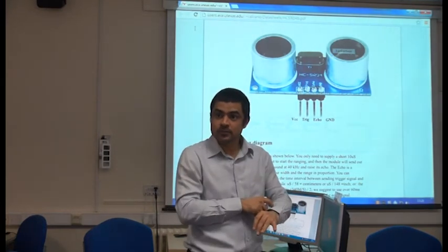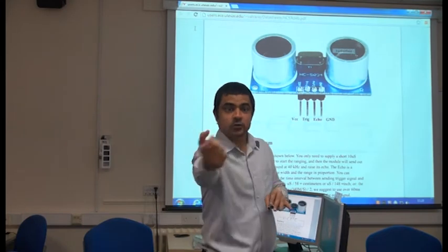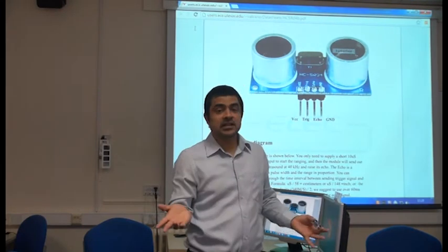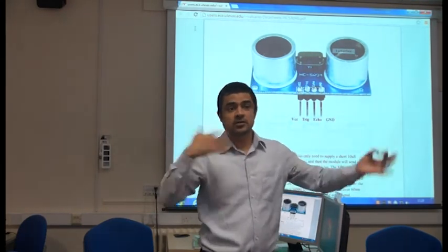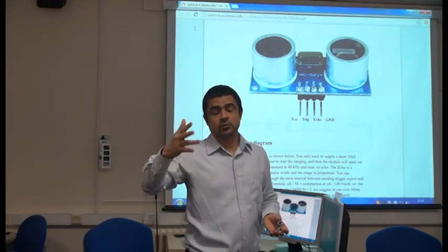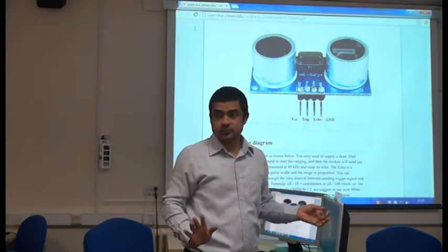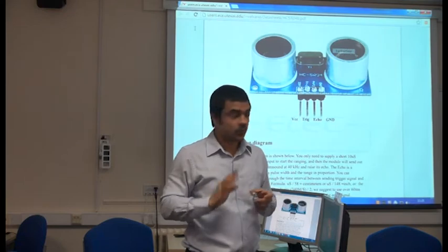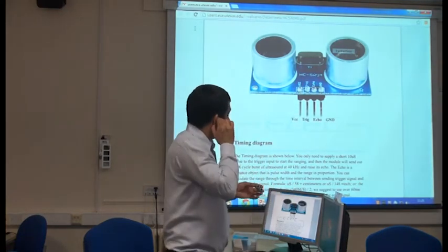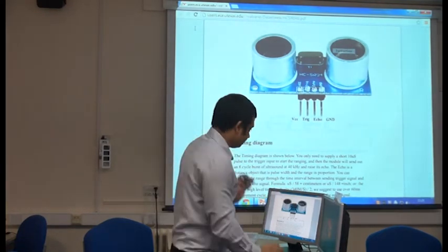So you will know the time, how much time it took for the packet to go and come back, and suppose that was 10 seconds, then your distance becomes 0.003 into whatever that is into 10 divided by 2. Is this basic concept clear to everybody? Okay, so that's how this sensor works.